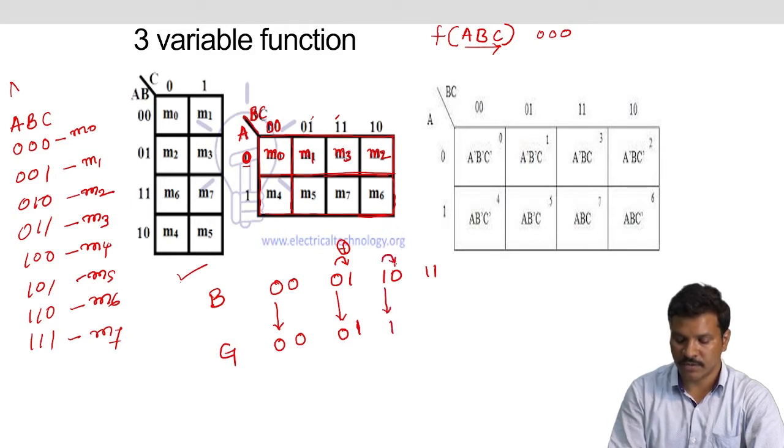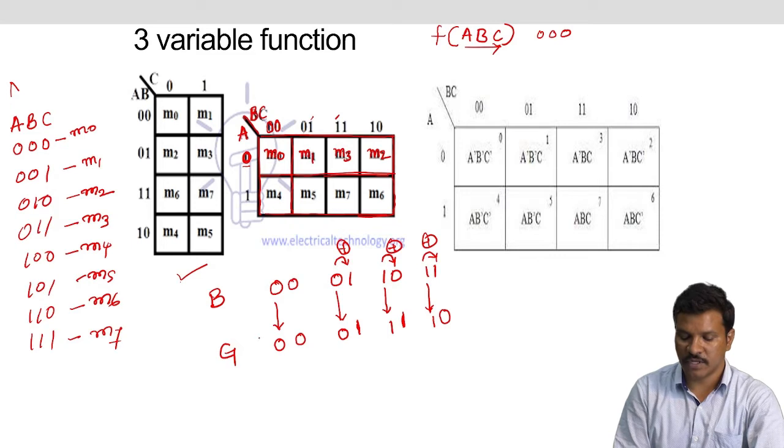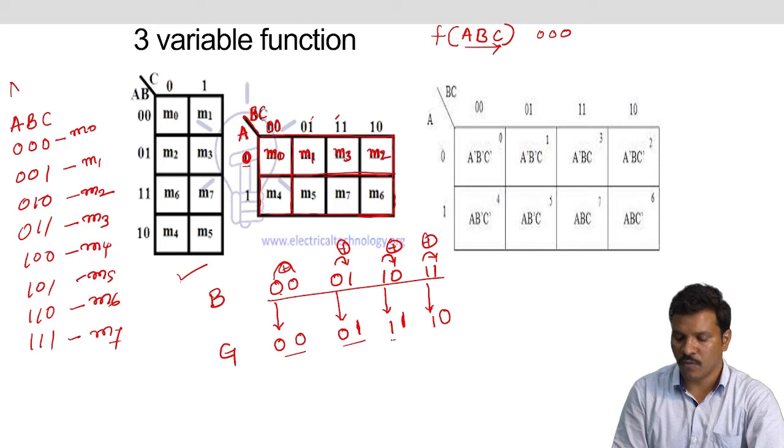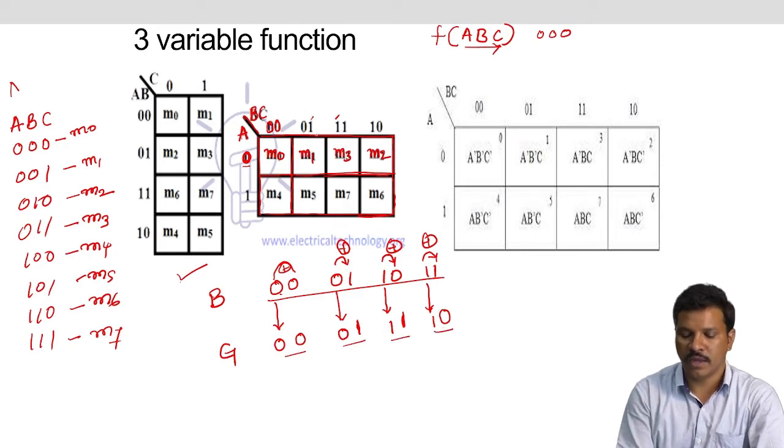Its XOR operation of 1 with 0 is 1 1 1, and take the MS bit as it is, and its XOR operation with the neighboring bit is 0. So converting the binary sequence 0 0 0 1 1 0 1 1, its corresponding gray code is 0 0 0 1 1 1 1 0. That's why here we are taking 0 0 0 1 1 1 1 0.